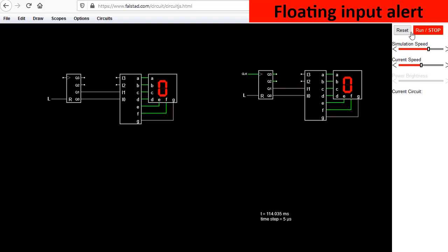For example, you know the construction of the input inside of a chip, and there's pull down or pull up resistor inside, or you've programmed your microcontroller so there's pull up or pull down resistor inside. Okay, so we'll fix that inputs, connecting them to low state, so ground, and those as well. So now we can continue.